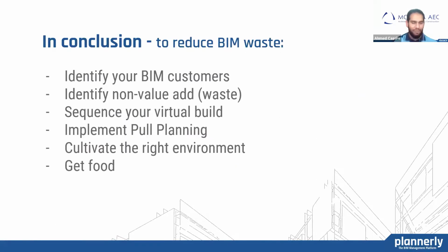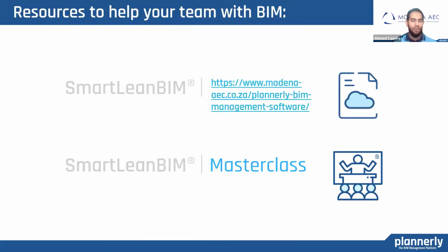So in conclusion, identify your BIM customers, not only the clients, but the teams in the project which you need to provide information to. Identify waste. Sequence your virtual build. Make sure to have a priority structure of which teams need to start and when. Implement pool planning. Cultivate the right environment, which is collaborative and informative, and get good food. Everybody likes food.